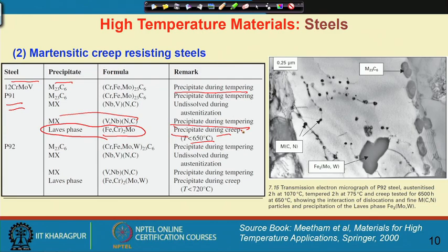And what we really do is a solution treatment in the austenite field, which means we take the steel to the austenite phase field, we quench it, we get martensite, we then temper it, so that we get the desired precipitate type in order to strengthen the steel.